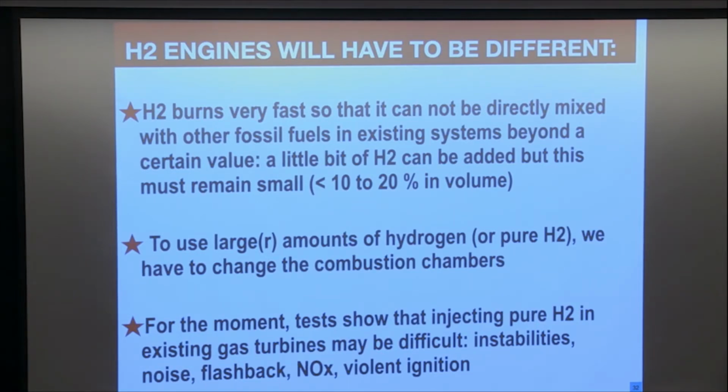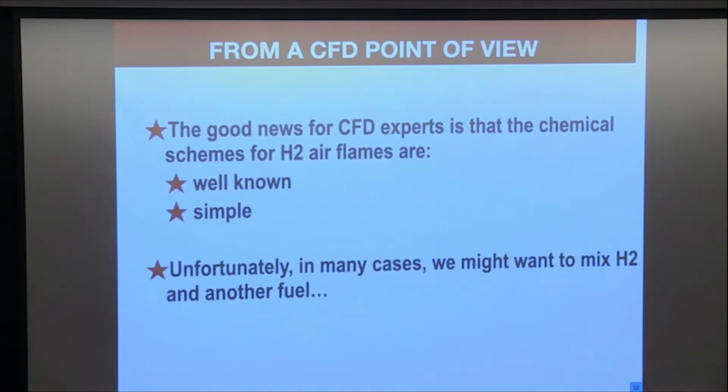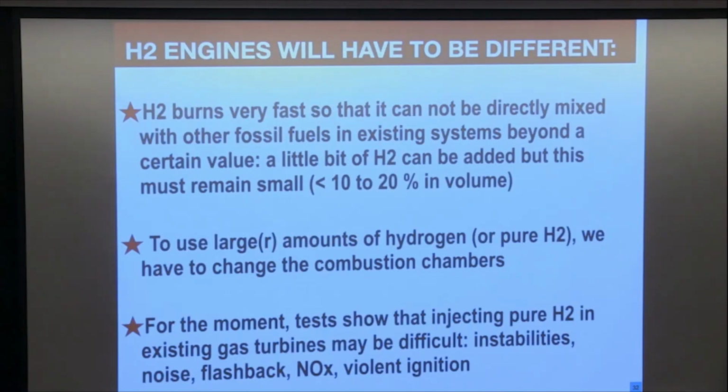And of course, because the power of H2 is very high, you usually have a lot of noise. Those are very noisy flames. In the lab in Toulouse, when you operate the H2 flames, you recognize them. They scream more, and they scream at higher frequencies because the time scales are shorter. Every time you have a more intense flame, you have more noise. Okay, I will continue after the break, but maybe we can take a few questions now if you want.